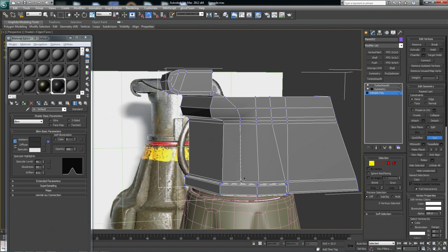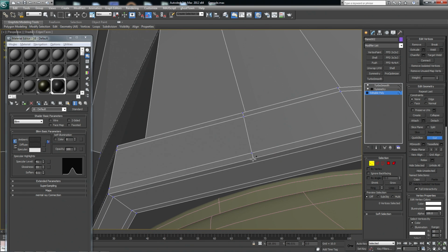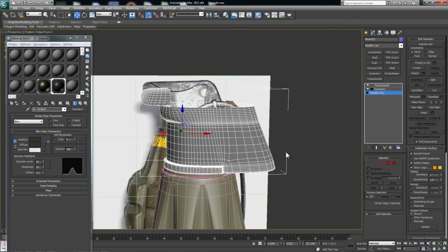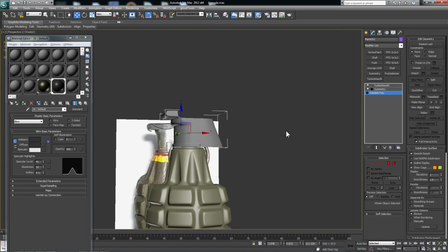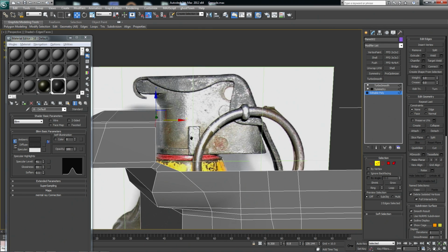Again, these are the types of issues you'll constantly be fighting with. Something isn't smoothing correctly, so you add a few edge loops to fix it, and then you realize those new edge loops introduce more problems that need their own solutions. More often than not, the solution is to either gradually space them out and manually smooth the curve, or to terminate the edge loops somewhere flat like the middle of a surface.